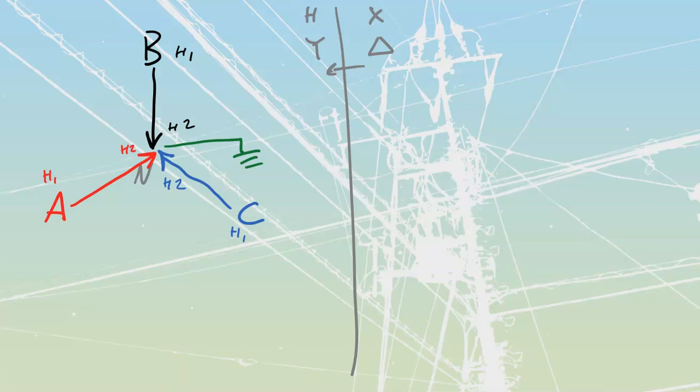And we know that on the low voltage side, we have this phase displacement. A to neutral looked like this on the high side, but on the low side, because we're changing from Y to delta, anytime it's a delta to Y or Y to delta, we have to move this up by 30 degrees. So we are now going to end up with it over there, which means that my A is going to be over here. That's where my A is, continuing around in a clockwise manner. I'm then going to place my B, and I'm going to place my C as well.